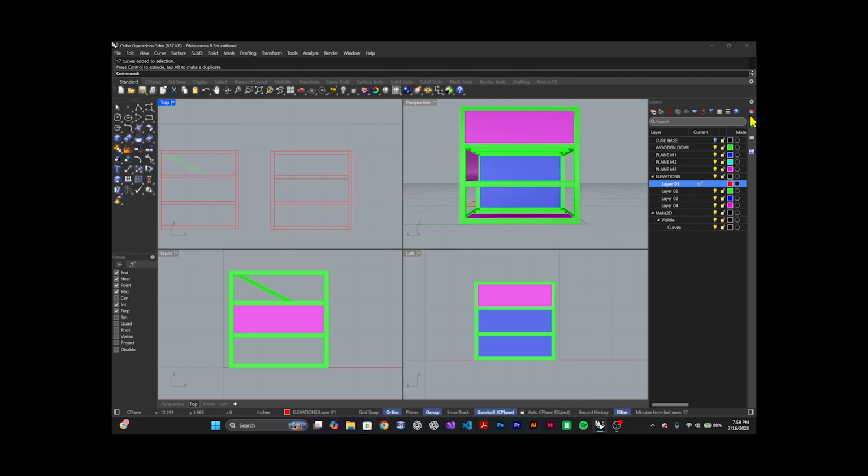Now we're gonna go ahead and select my second layer, and then we're gonna represent the planes with hatches, okay? So I'm gonna do hatch. I'm gonna take a hatch. Then boundary, yes. Now we select everything, enter. And now it's gonna let you click inside the regions that you guys want to do the hatches, okay?